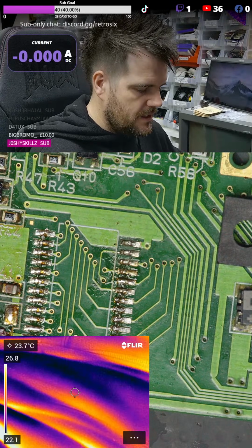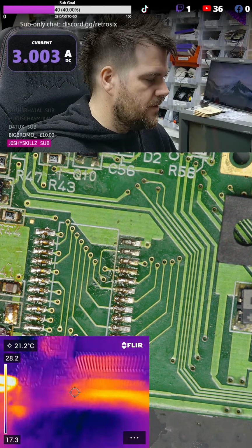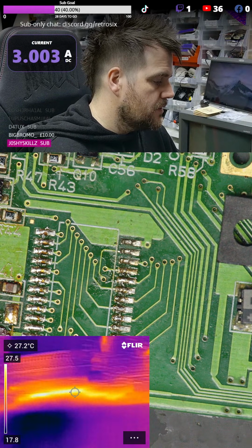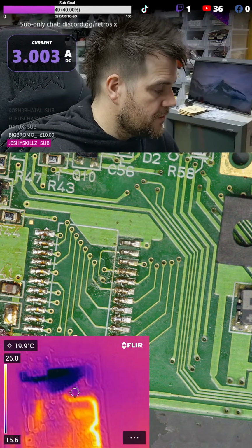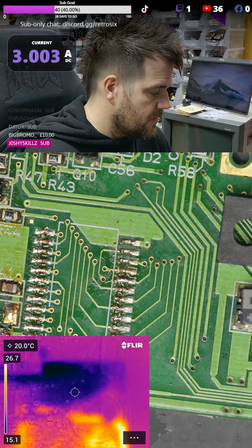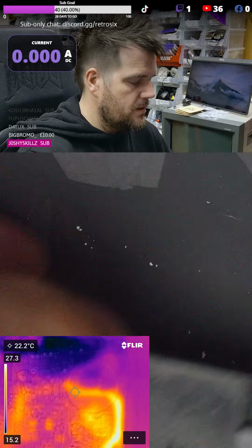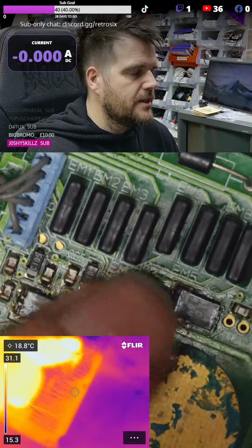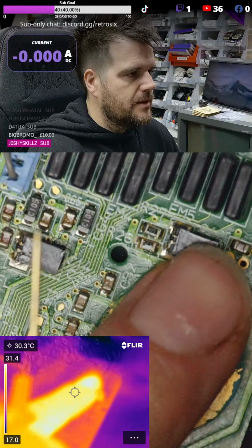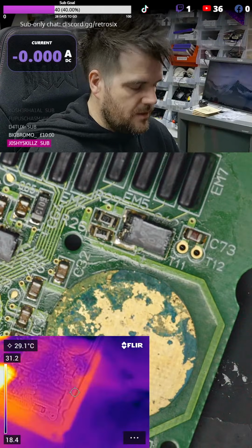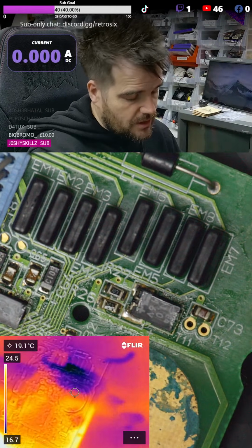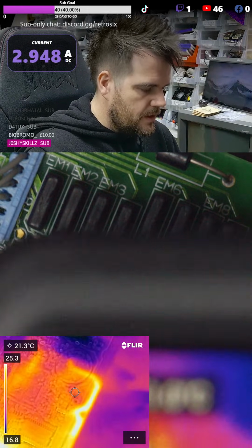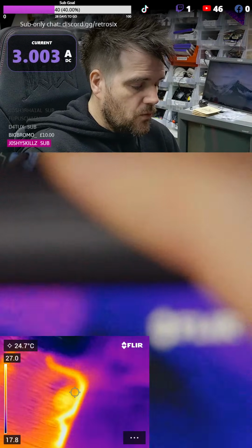And the reason you know that is because if you go over where it is, and you kind of go around, you want to go to where it fails. So you go all the way around, all the way up, you go up to the top, and then you zoom in close, and you're failing somewhere, effectively, up here. So this is where it's taken us to, somewhere around here. So you might suspect this capacitor here. We obviously know the short is the other side of a dead short, but if we inject the voltage back in and watch it warm up, you can see this is the trace getting warm.